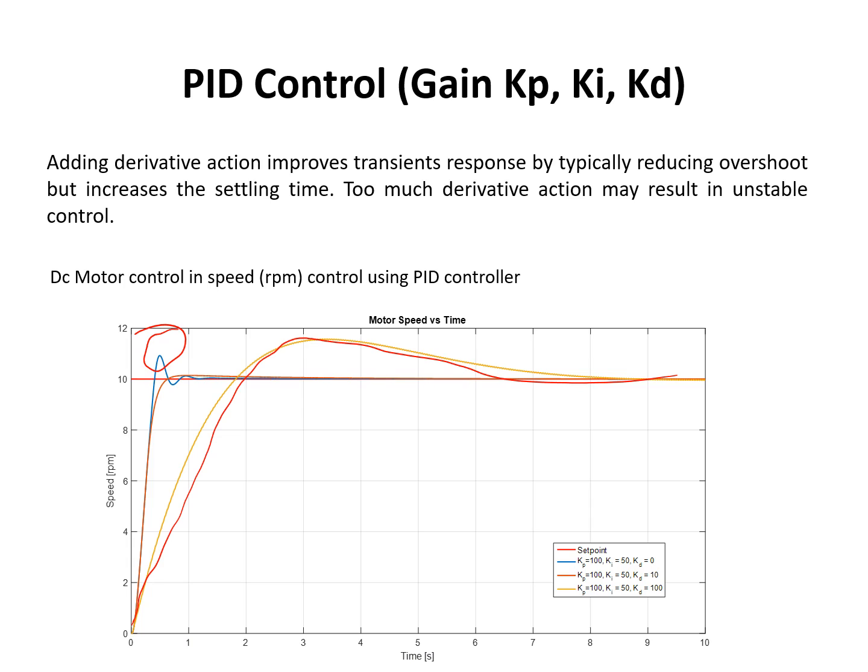In that instance, you don't have to add an integral term. The integral term is just going to give you additional overshoot and slow down the response, whereas if you have a steady state error which is not 0, that's when you want to add an integral term. So you only have the integral term when you have a steady state error which is not 0 with a proportional controller.